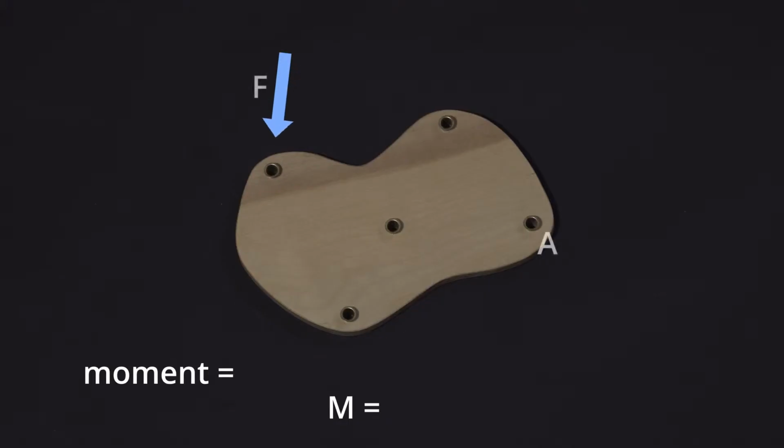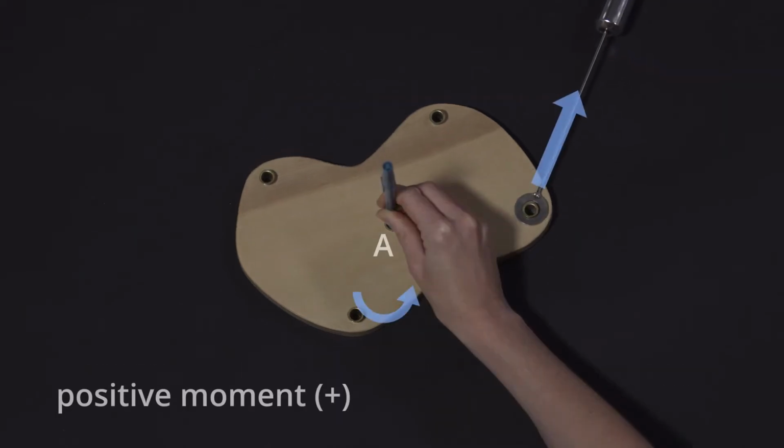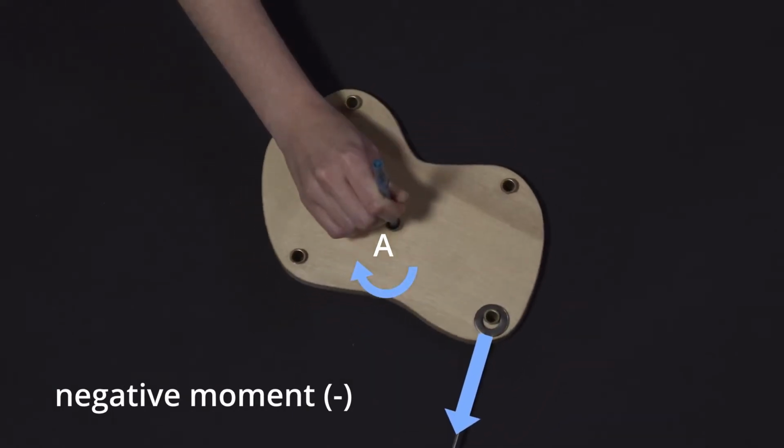More specifically, we multiply force and distance together. The distance we use is the perpendicular distance from the line of action of the force to the point A. This is the same as the shortest distance between point A and the line of action of the force. By convention, we call moments that are counterclockwise positive and clockwise moments negative.